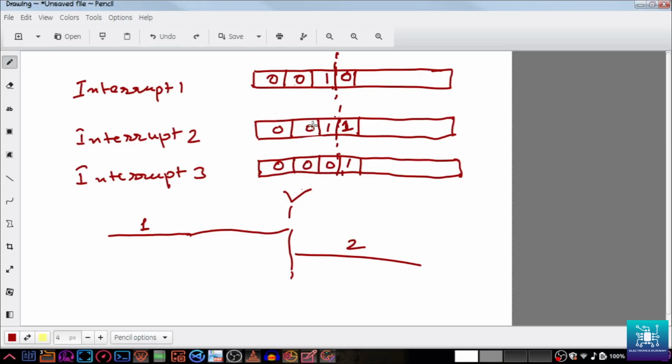This is the logic of how sub priority works. These two both have a group priority of 1, so which interrupt executes first is decided by the sub priority field. Now if both these interrupts had the same set of bits, then the Cortex M4 will refer to the interrupt vector table and check the IRQ numbers. Whichever has a lower IRQ number is going to be executed first.